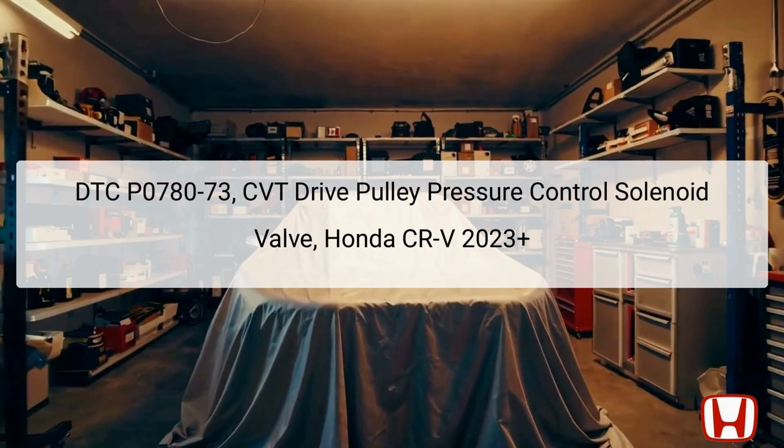The solenoid is located within the valve body assembly, which houses numerous critical components that manage fluid flow and transmission function. The Transmission Control Module, TCM, monitors transmission operations and stores this DTC if it detects that the pulley ratio is out of its specified range, either when the vehicle is stationary or in motion. Understanding the exact implications of this error code is essential for effective troubleshooting and resolution.